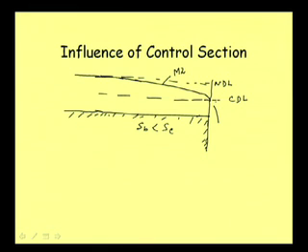There is some difference, but approximately we can consider that this is equal to critical depth. Now from here we are starting at critical depth, and this is our downstream point. As the depth is greater than critical depth along the entire flow profile, it is subcritical flow.